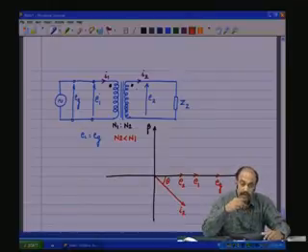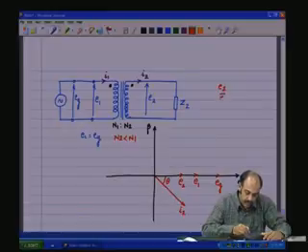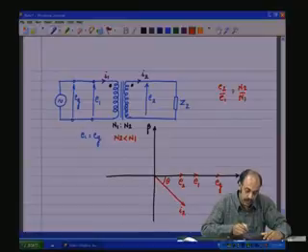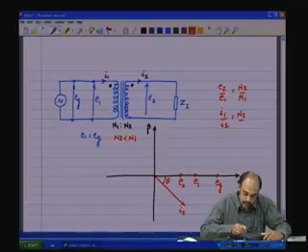What happens to I1? Now, we see that N2 is less than N1. We know that E2 by E1 equals N2 by N1. So, E2 is N2 by N1 into E1, which is less than E1. And I1 by I2 equals N2 by N1, this is the inverse proportionality.